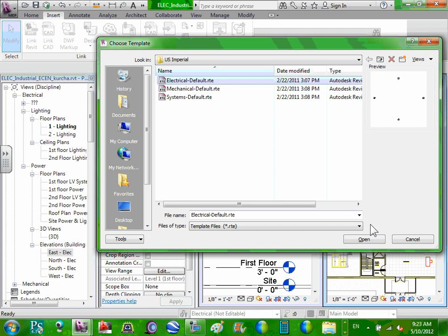Okay. And now at that beginning stage, what we do is we get the architect's model, and they've got, say, 4 levels. We open up our template, we match our level 1 with their level 1, our level 2 with their level 2. We match all those up right from the start, blast away the 3 that we didn't need because we've got 7 preset, and then we're creating our file. So there's the fundamental setup thing. The setup is the most important thing with a Revit project.